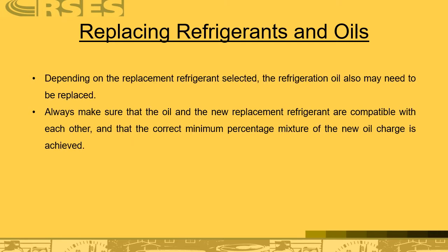Depending on the replacement refrigerant selected, the refrigeration oil may also need to be replaced. Always make sure the oil and the new replacement refrigerant are compatible with each other and the correct minimum percentage of the new oil charge is achieved. Once again, taking a compressor out of a 20-year-old system and changing the oil to, say, as an example, POE is a royal pain.